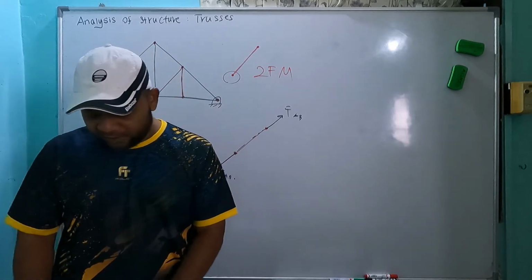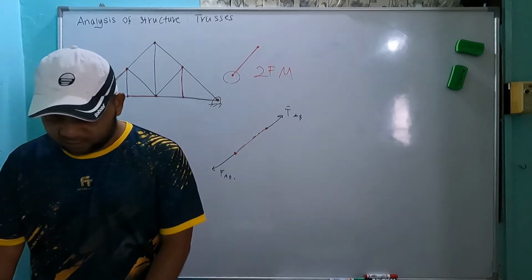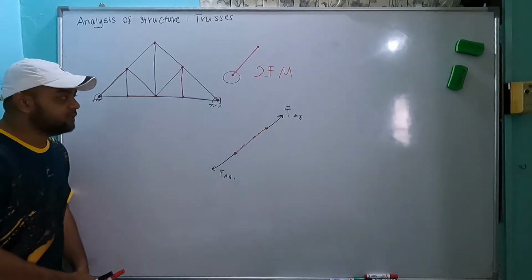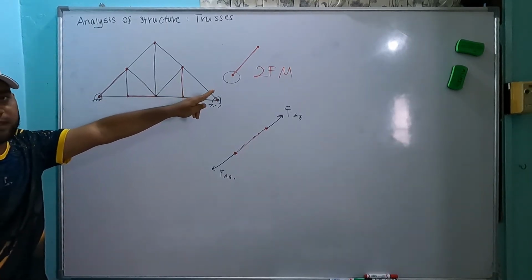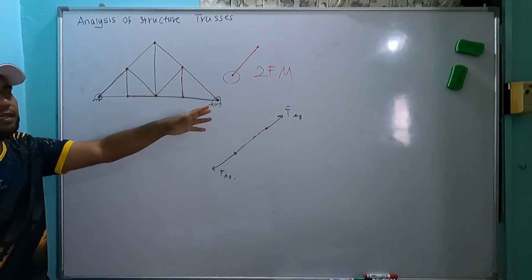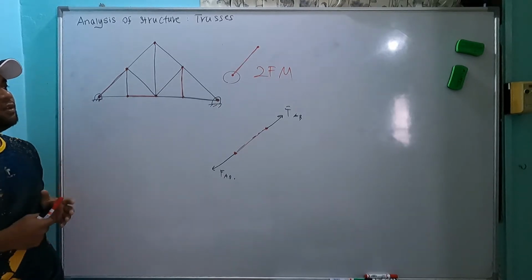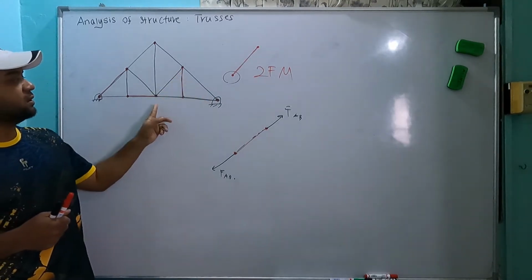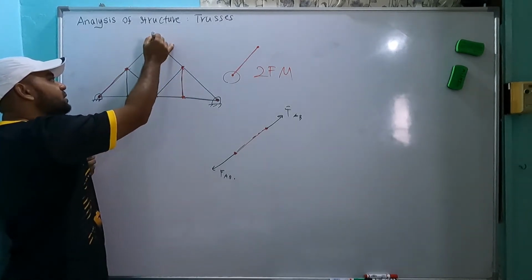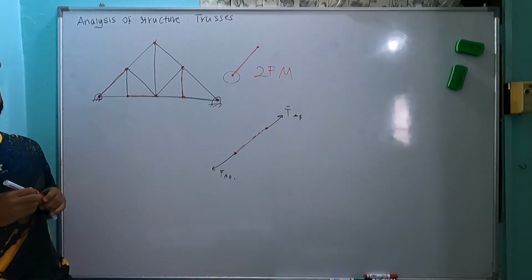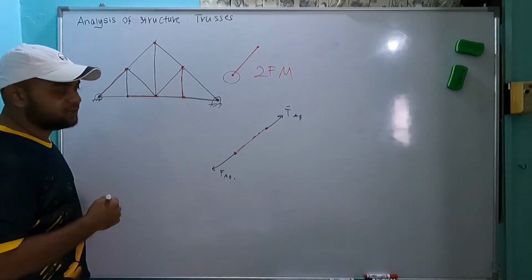So we have two methods to solve this one. Okay, so again, trusses are made up from one simple component like this one, which is a two force member, combined together to become a big structure. Even though in reality this joint is normally welded, fixed, in our syllabus we consider that all the joints here are pin joints.